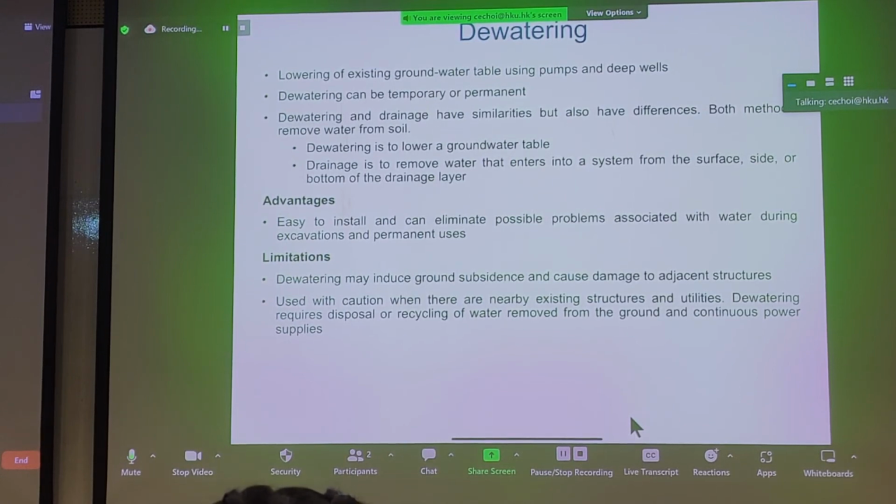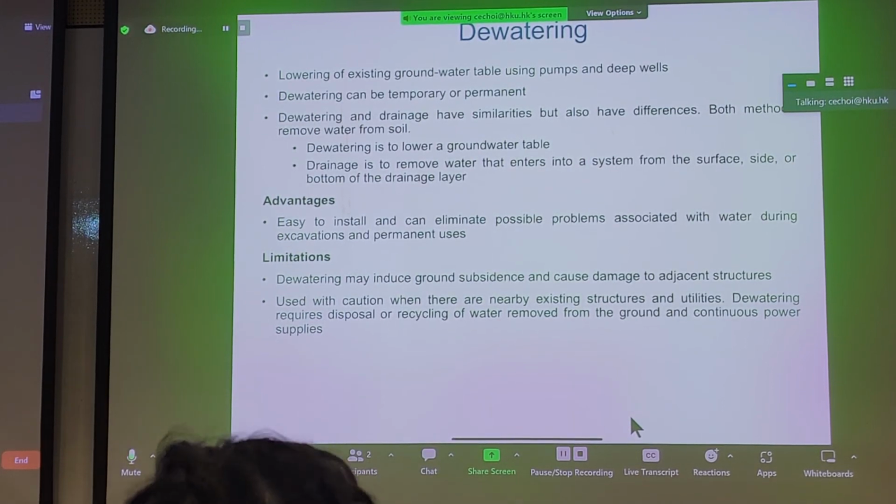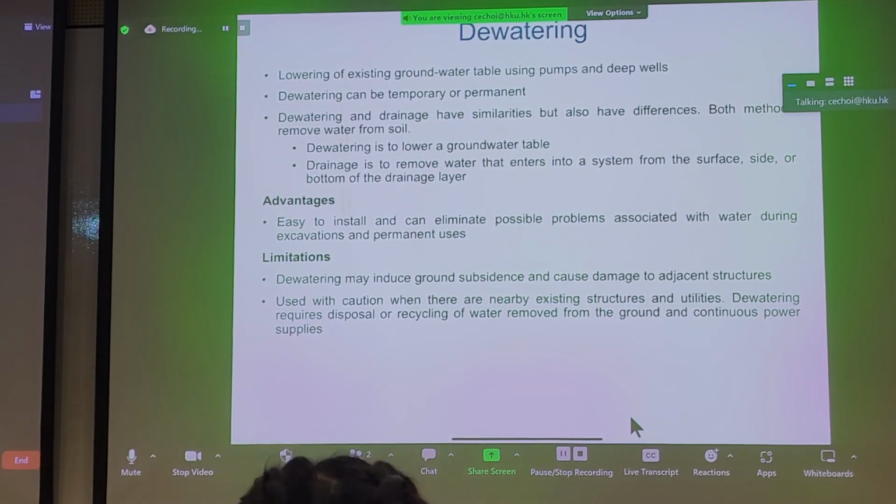Back to dewatering. So the essence of dewatering is to pump down the groundwater table because we want to increase effective stress, or we just need to temporarily get into an excavation. And I talked about some of these points already. So essentially we're installing pumps at different elevations, different types of pumps, centrifugal, pneumatic, electric pumps, sump pumps, anything we can to suppress the groundwater table.